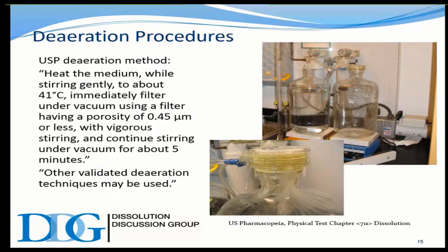Again, this is probably considered a bit of a gold standard. It is based on a very simple concept of boiling. The most efficient way to strip air out is literally to boil it. And by doing so, you see bubbles coming up and it's relieved. But this is totally impractical for the laboratory because of the huge energy it would take to heat up 50 liters. Boiling it is very unsafe. Imagine that much boiling water around. And then it would take so long to cool down that it's just impractical.